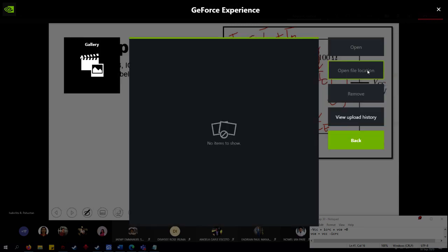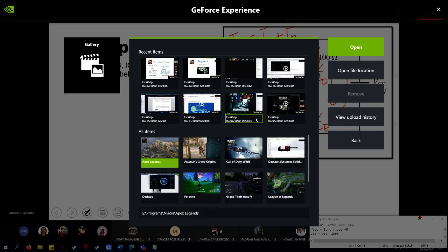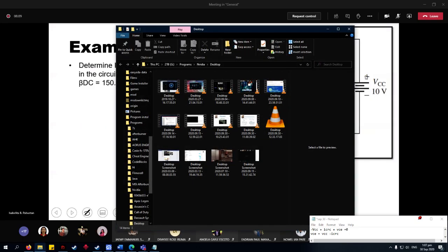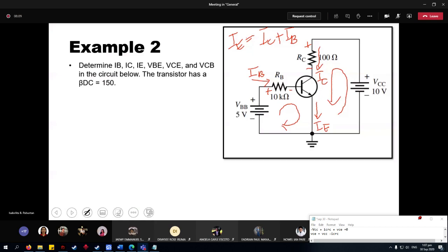We still have another voltage on the input loop. You have the VBE. Since this one is an NPN, N emitter, P base, the polarity here for the VBE will be like that. So, this is the VBE. So, when you solve that, you are being asked for IB.